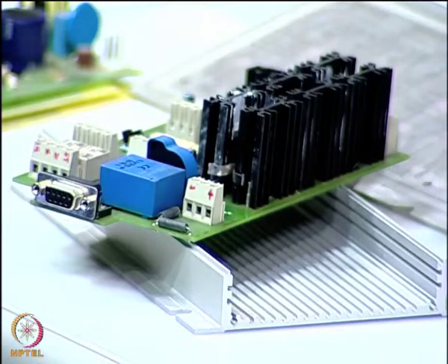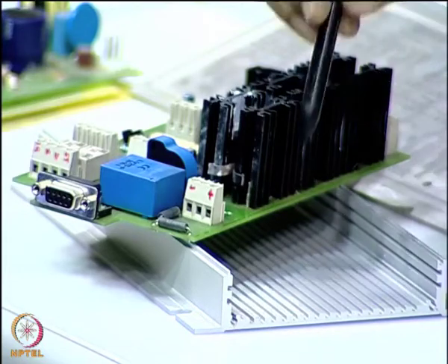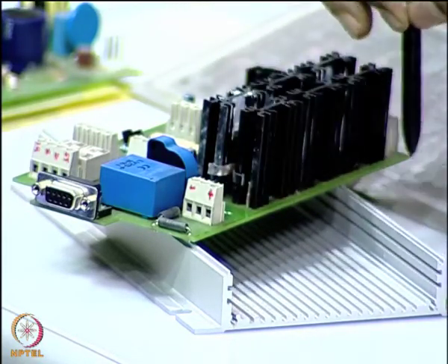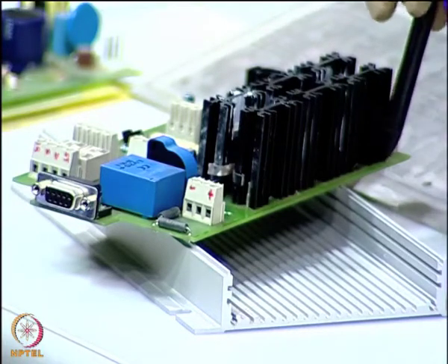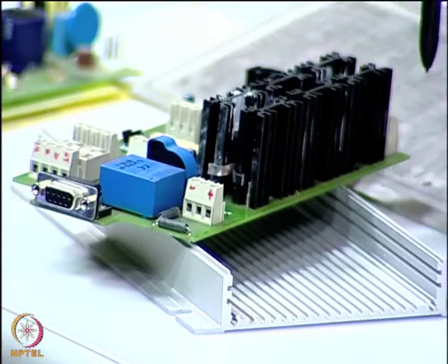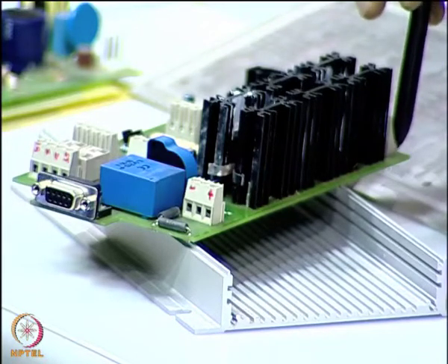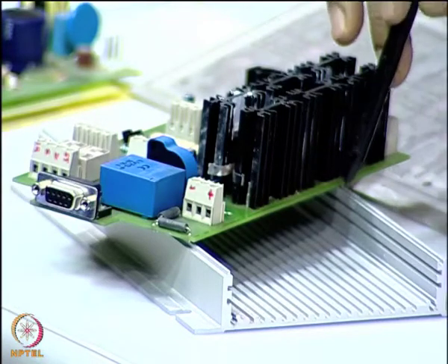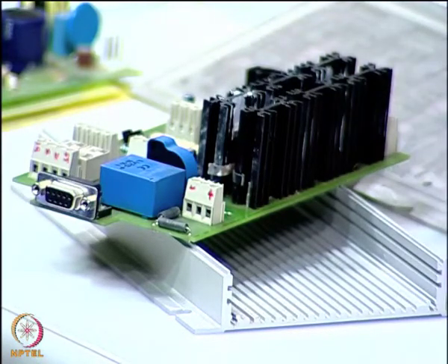That amount of space, about 2 mm, should be clear, with no track routing on these edges. At most, if it is not possible to manage, you could have a ground track going along these edges. Otherwise, it is advisable not to have any tracks.